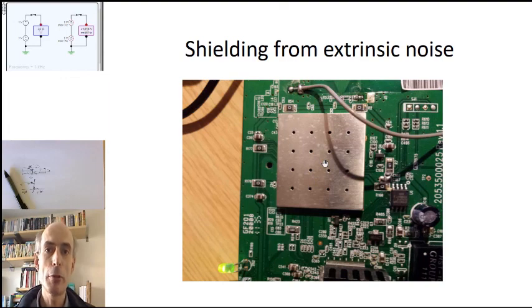Noise coupled in from the power supply can be reduced by careful filtering of the power supply as it arrives. You can get noise coupling in from communication wires as well, and careful filtering of the communication wires can help with those. External magnetic fields are somewhat harder to deal with. It's harder to shield them out, but you can reduce their effect with appropriate design techniques.